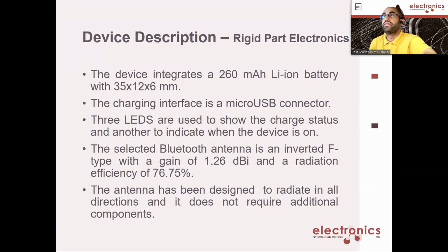The device integrates a lithium-ion battery of 260 mAh with a size of 35 by 12 by 6 mm. The device also has a micro USB connector as charging interface for using a standard 5 volts charger for electronics. It also has 3 LEDs to show the charge status and another one to indicate when the device is on.